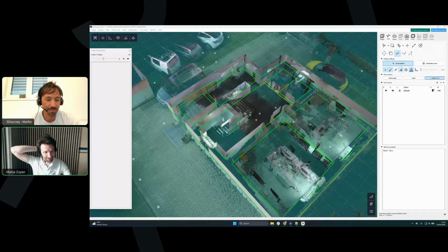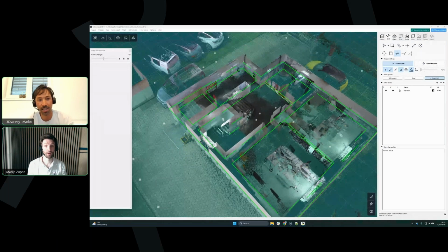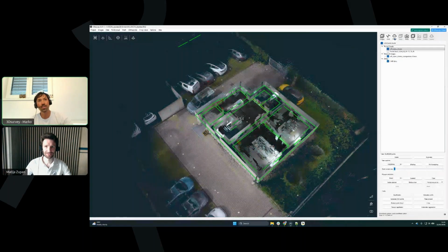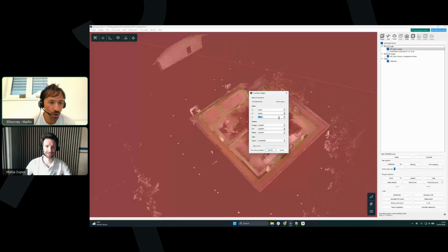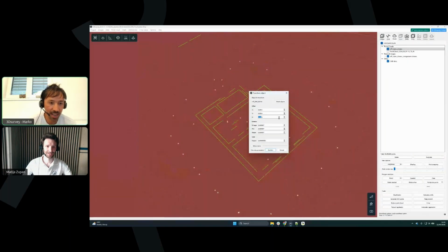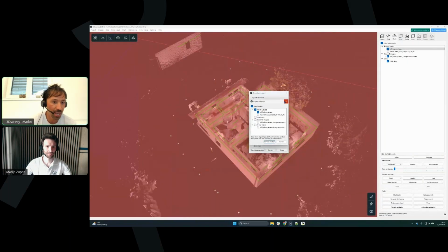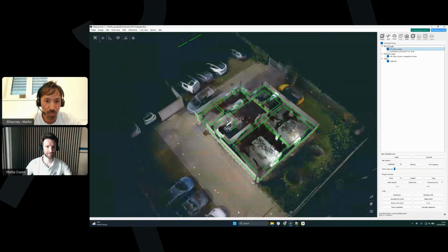For example, if you wanted to reverse the last scenario and you need to output your DXF CAD data on the zero elevation, you can do the same trick as I showed you. Exactly. And then beside this, you have also transform options. So right click on the data and transform it lower for 100 meters or transform to specific height or anything like that. So all this is possible. Also, when you'd like to export the CAD data, it's ready for you there. Just go save CAD data as DXF, TXT, anything like that. All the standard file formats are covered.